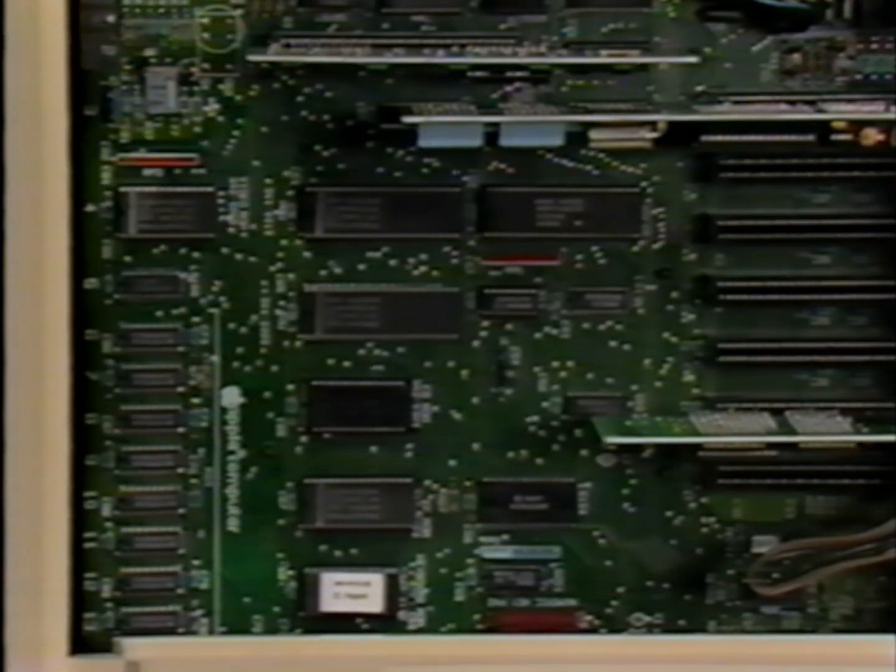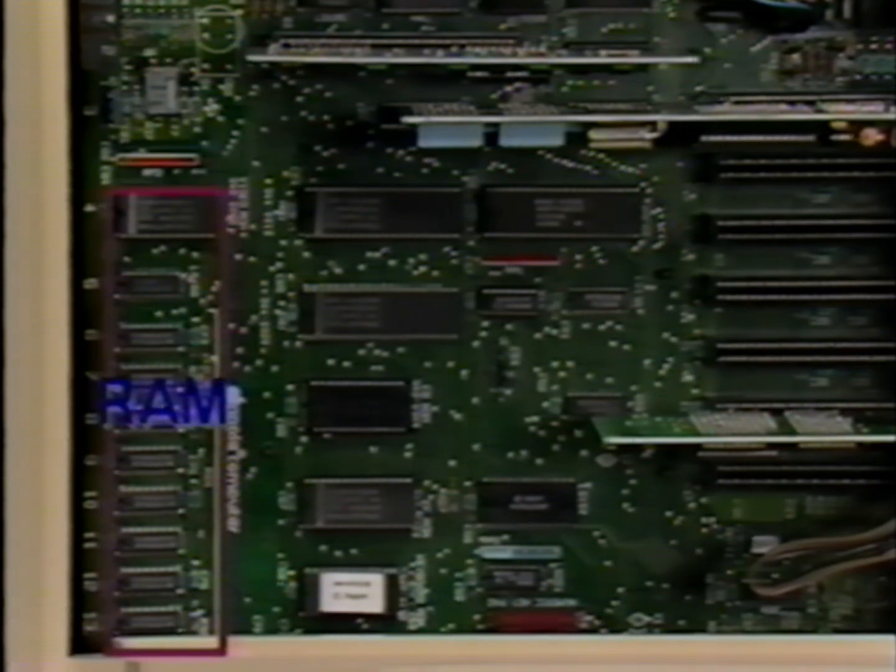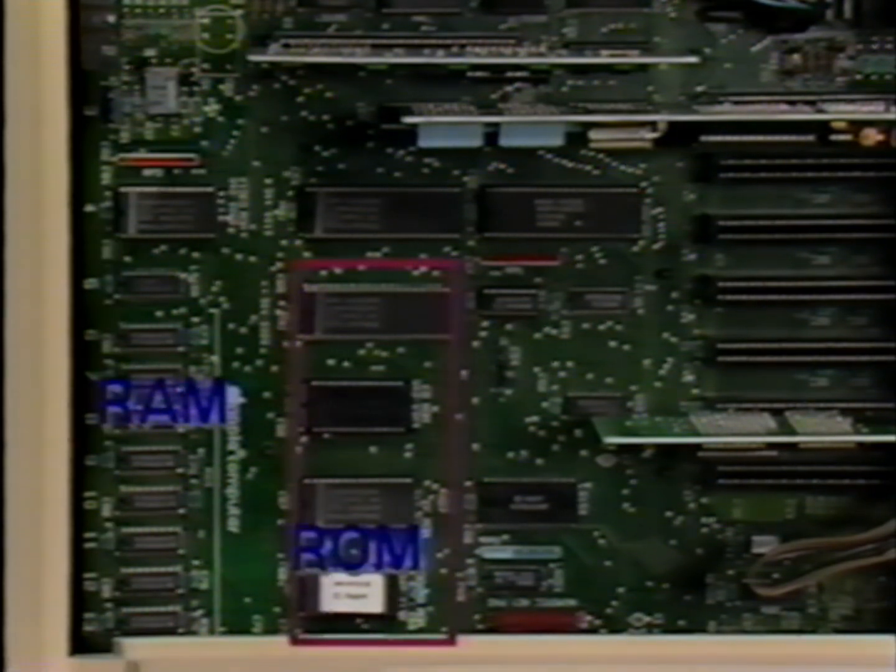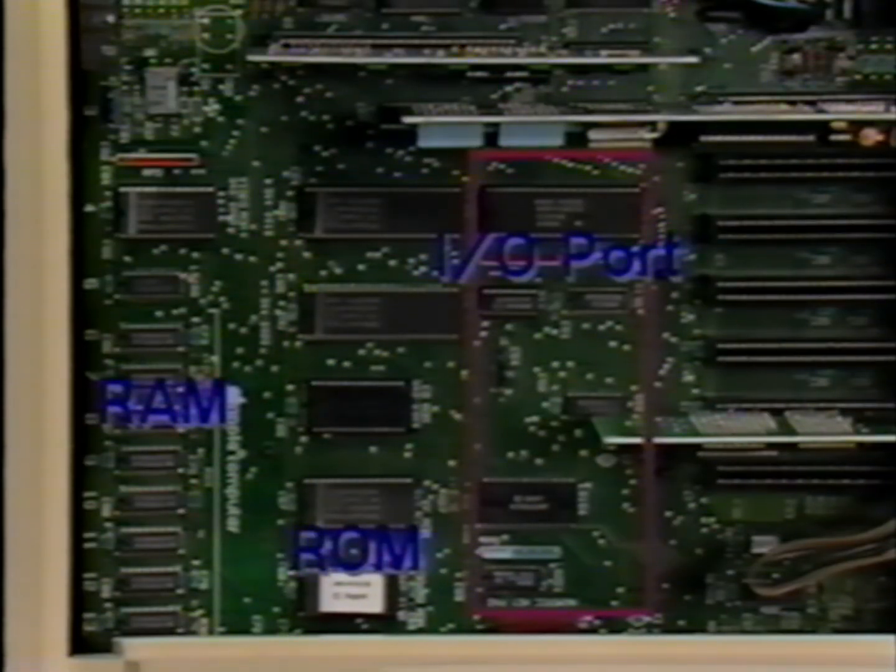Desktop computers, on the other hand, always use separate chips for each of the major components. You'll find that the RAM, ROM, and I/O port chips are separate from the microprocessor. Because the primary role of the desktop computer is to manipulate large amounts of data, this requires very large programs, large amounts of memory, and several serial and parallel I/O ports. We'll be looking at microcontrollers used in two typical applications, the VCR and the compact disc player.